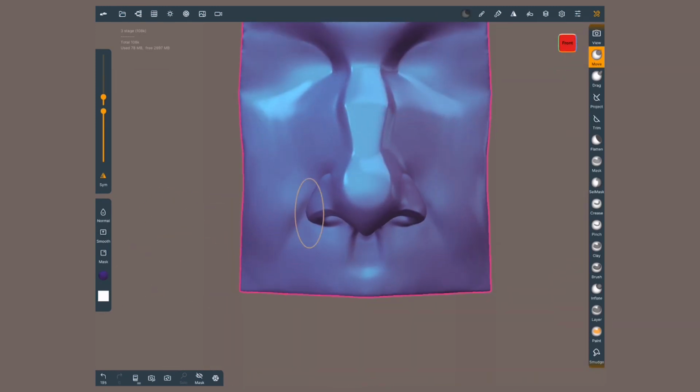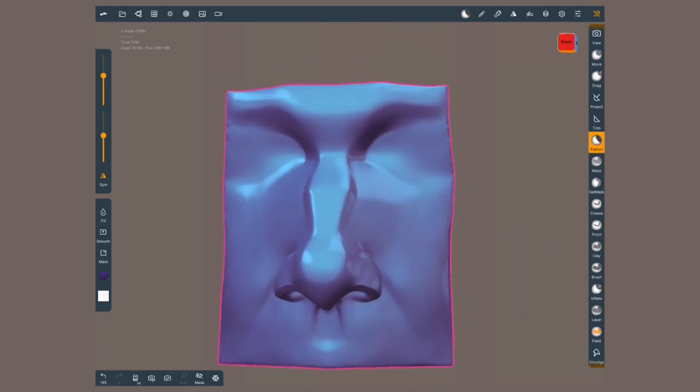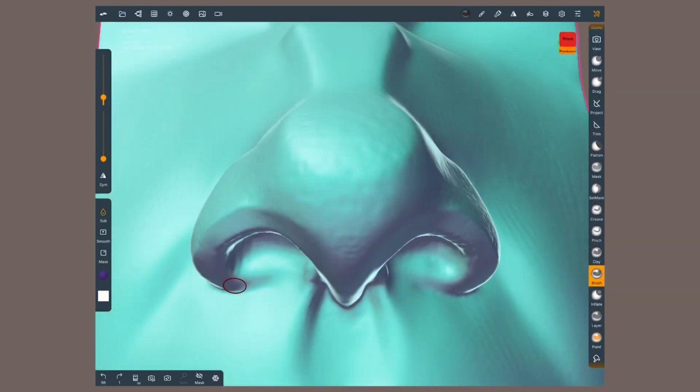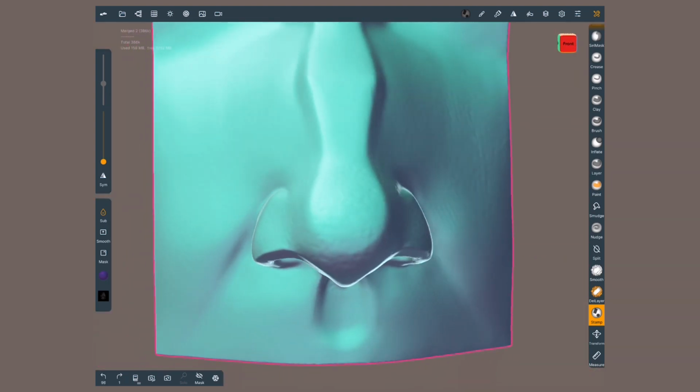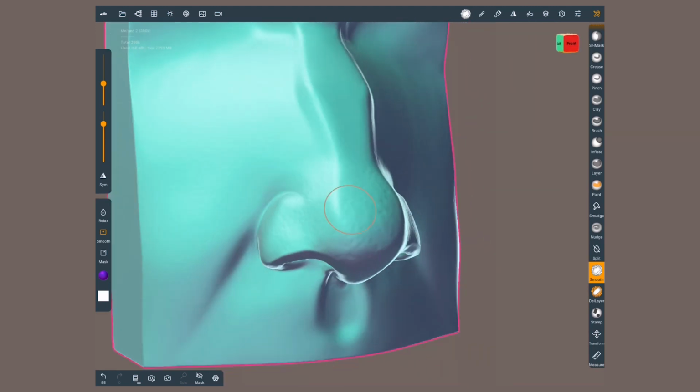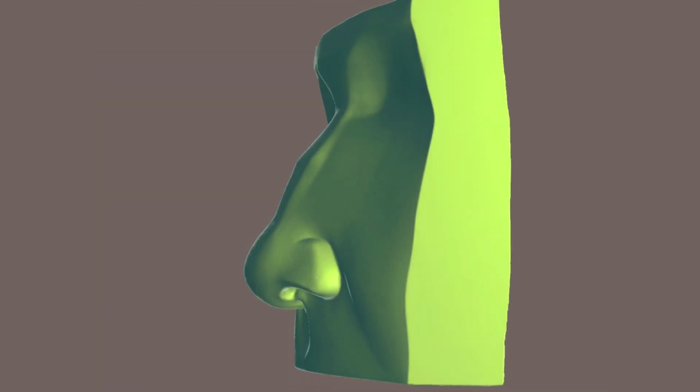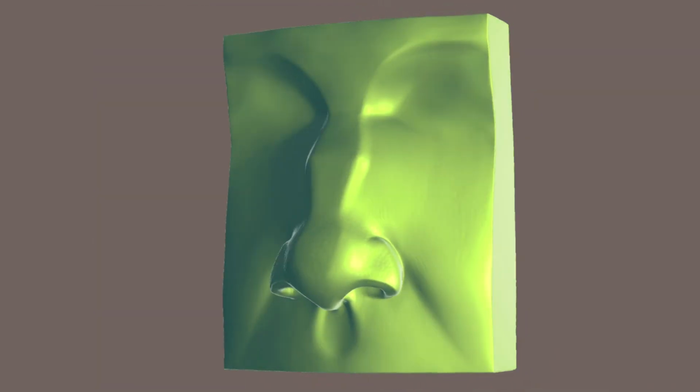Voxel remesh again or use dynamic topology if you need more detail. Go higher when your silhouette works and your surfaces are smooth. Higher resolutions are harder to fix. Use them where you're ready for details like pores or wrinkles. So, here we go! The final result.